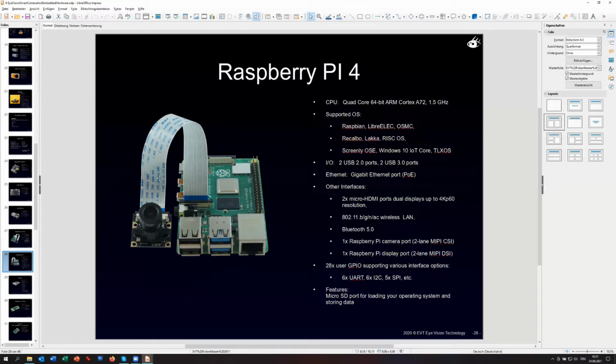Based on the standardization of the MIPI interface, you have an option of a lot of different sensor modules from 640 by 480 to 13 megapixel with either CS mount or C mount or with no mount.